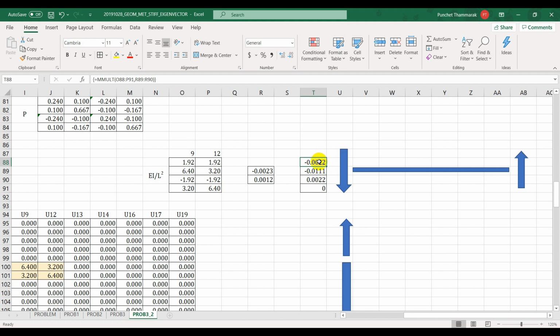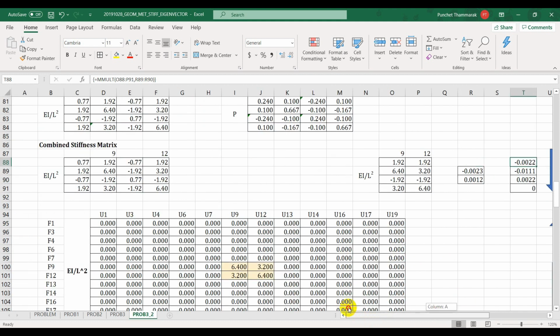This one will reduce your column axial force, and this one will increase the right hand side column axial force. So we can do some correction. It could be the iterative solution for now. So make this correction. You add this amount to the column on the left hand side.